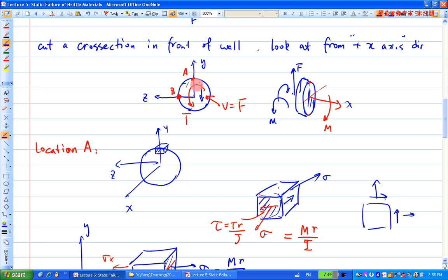They all feel the torsional shear stress, right? They just don't feel the same thing: one feels the M, but the other feels the V. So according to experience, the bending normal stress caused by the M generally has a more critical effect on the cross section than the V at this location.